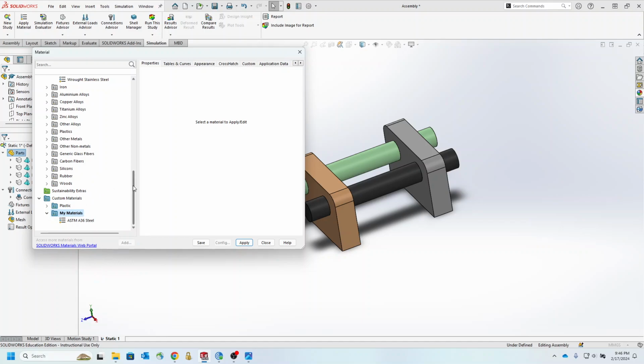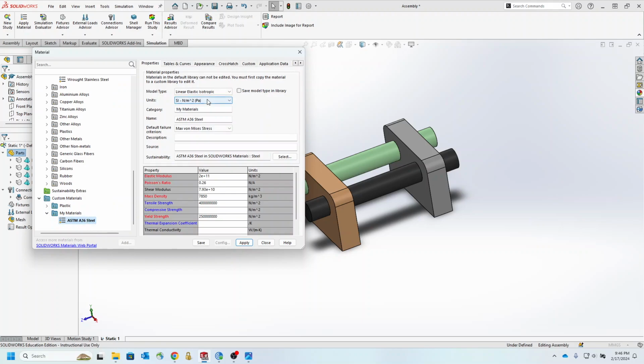Then the material that I have selected would arrive here. And here I'm going to change it. For example, I would call it structural steel. And then I can define this one based on the value that I would like to change. Going to select here based on 0.3.